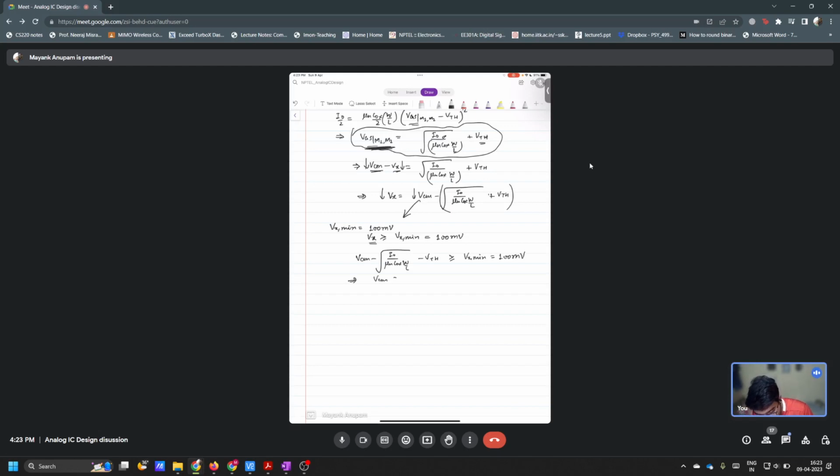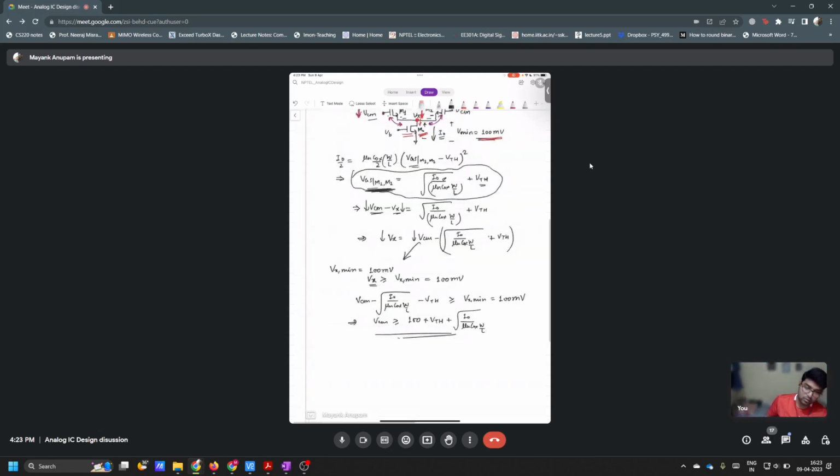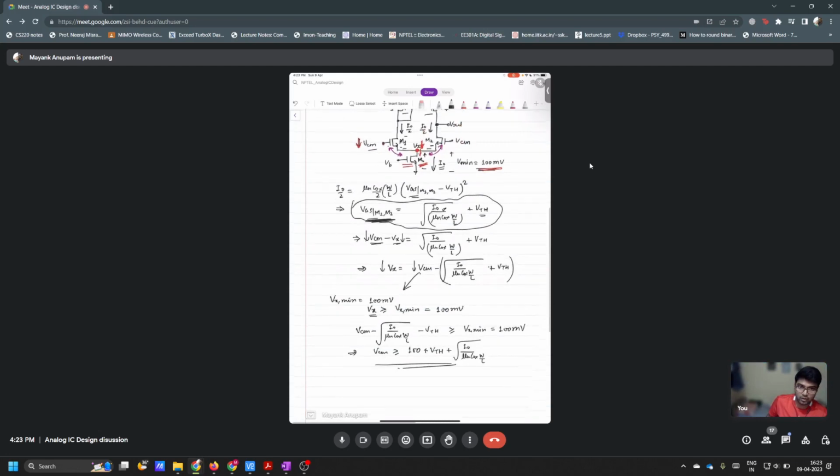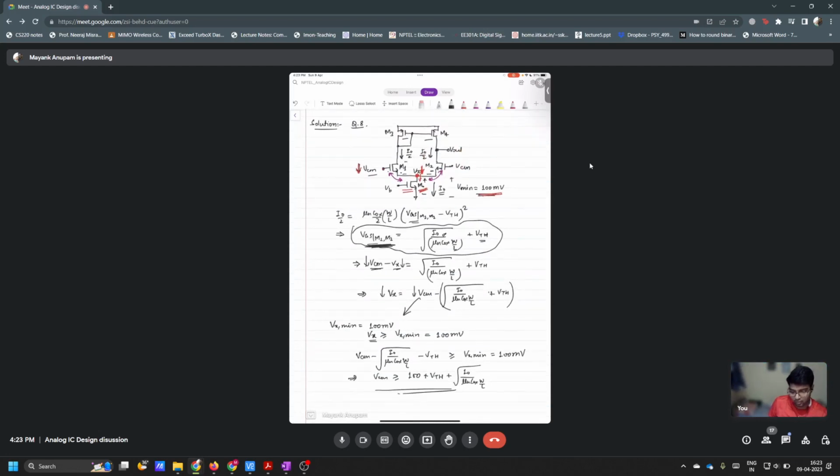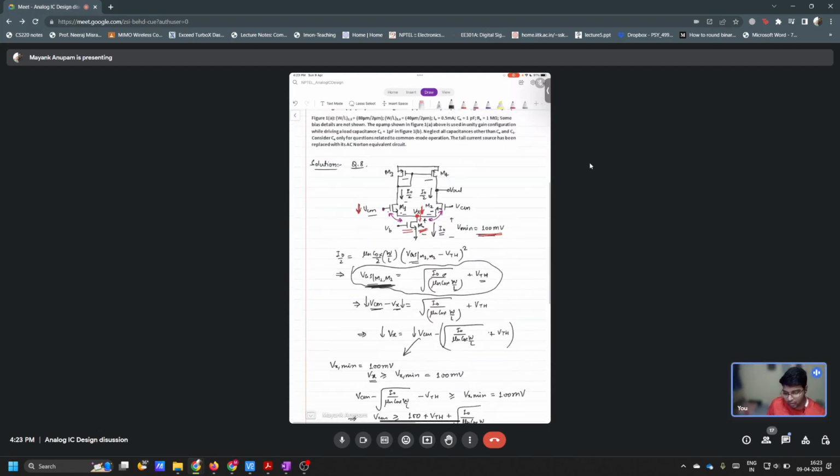So you will get some minimum value of VCM, which is equal to 100 millivolts plus VTH plus the square root of I naught over mu n Cox W over L, right? You understood, right? And now tell me what should be the maximum possible value of VCM. So how will you do that?